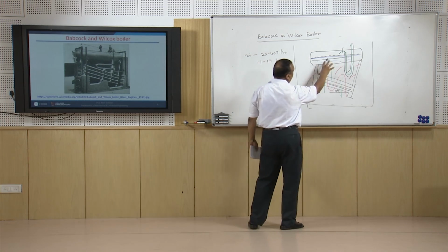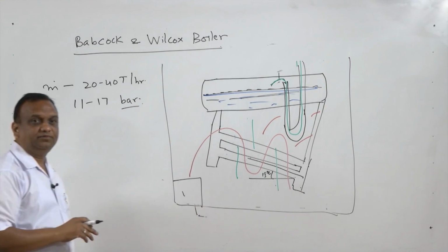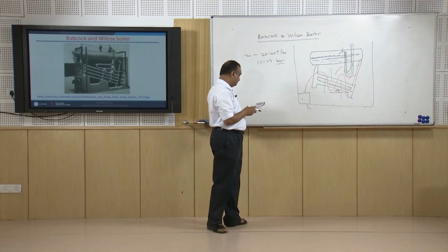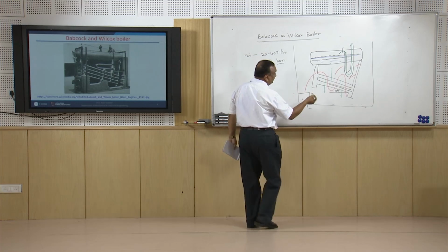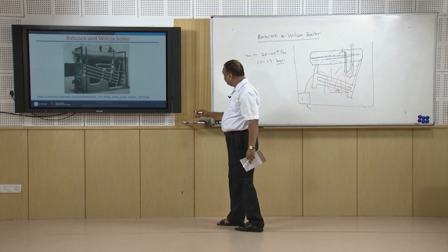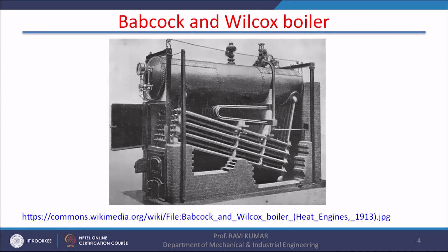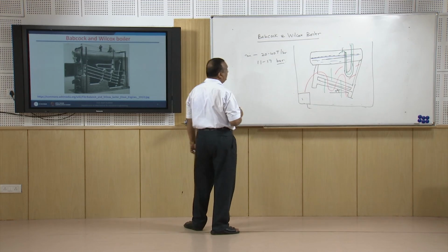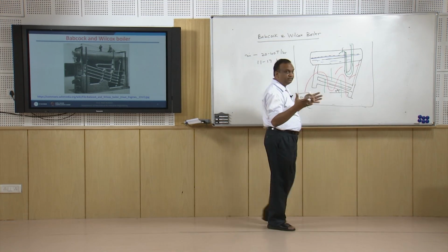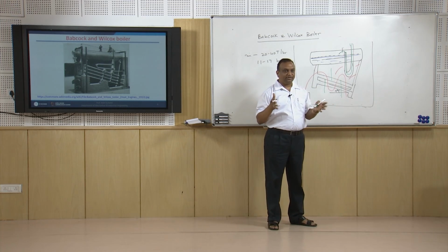In this boiler, because it also works on natural convection, the pressure loss is minimum. Because there is a lot of space inside the shell, inside the boiler housing, defective tubes can be easily replaced. The entire system is supported on the iron structure.